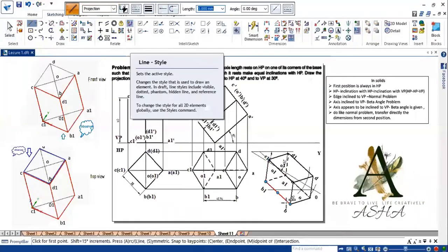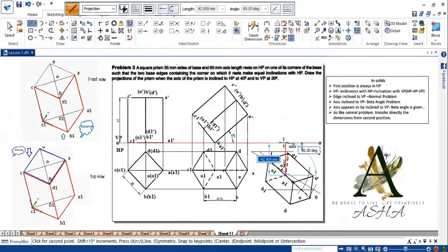Now in order to get the final projected view, use the projection line. A1 is here. So A1 will be on the XY line. So this is point A1. B1, that is the point B1. C1 projected onto C1. Then D1, so we have drawn A1, B1, C1, D1.